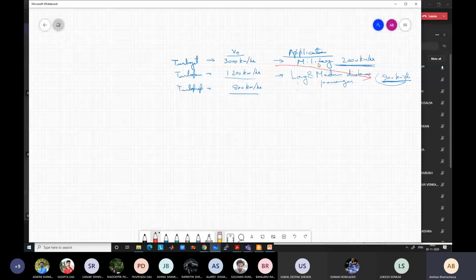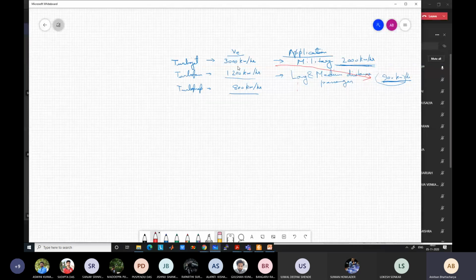So it will provide a lot of thrust: m dot into (V minus Vi). So this is Vi, right? These values that I am writing are the Vi values. So thrust is m dot into (V minus Vi). Because V minus Vi will be large, turbojet will provide a lot of thrust in this case, even better than this military aircraft.